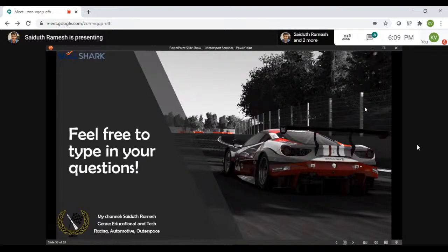When it rains also, the treads in road tires create channels for water to flow through. So instead of the tire creating some sort of water barrier between the rubber of the tire and the surface of the road, and by the way, if that happens, the car will start sliding. It's called aquaplaning. So you don't want these sort of things, and that's basically why we have grooves in the road tires. That's one difference. The second difference is the construction of the tire itself.